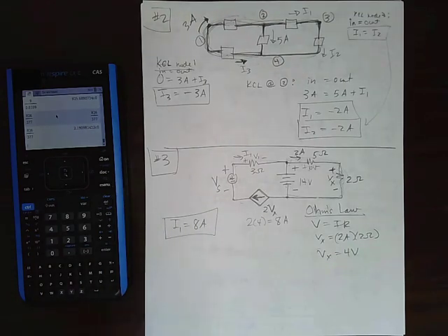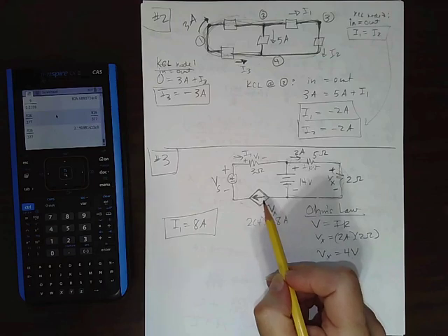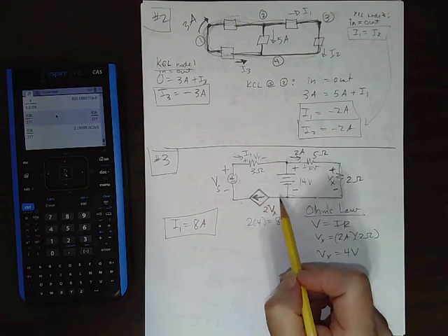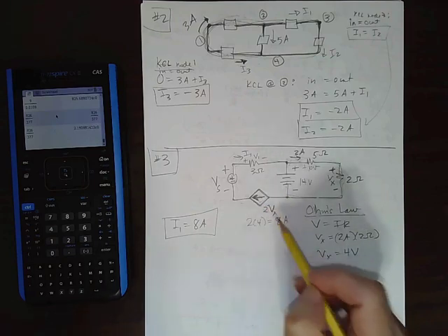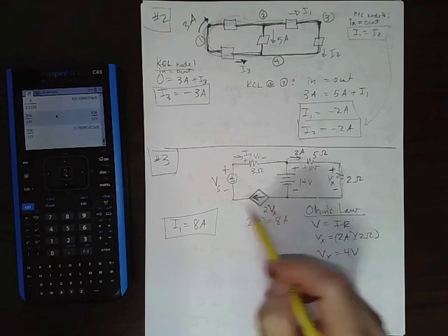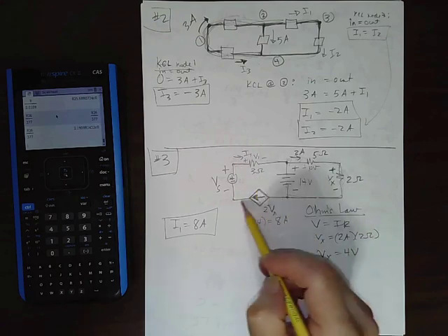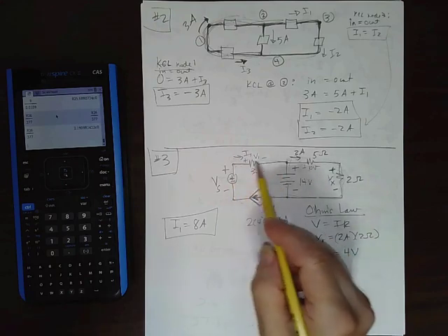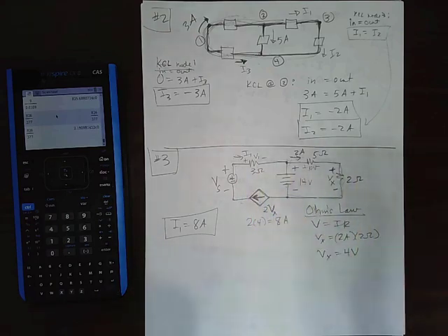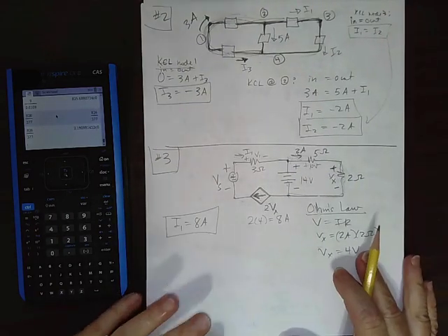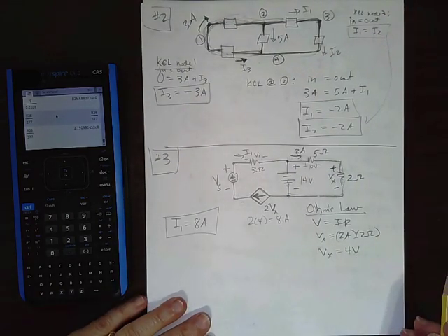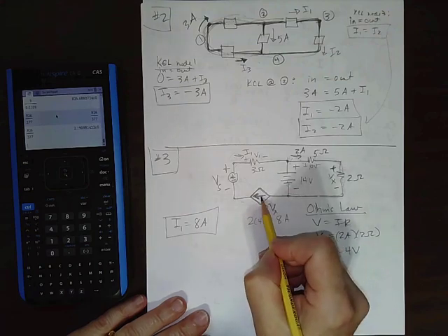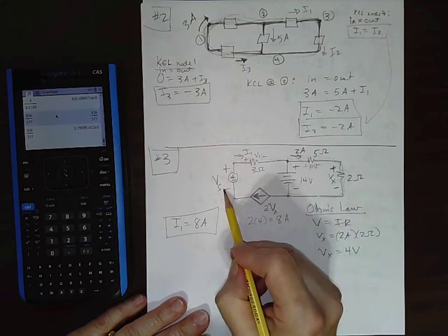All right, just from this current source says that its current is what the current is through it, okay, and so the current through it has to be the current through this source and this resistor. It doesn't have anywhere else to go, so it is 8 amps. Alrighty, and then what else can we do? Can we find Vs?